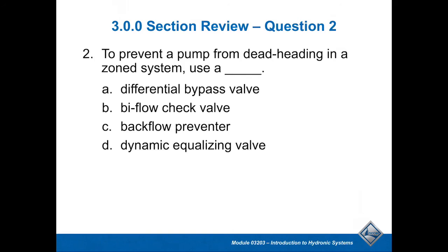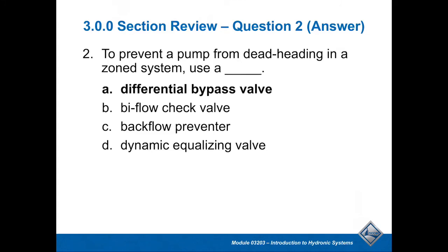Now this one we didn't talk a whole lot about, but there's a couple of things that we would do. Deadheading is a term we use for when the pump is running, but there's no place for it to go. You've deadheaded the pump. So to prevent that from happening, a lot of times they'll use these differential bypasses to kind of fix that to some extent.